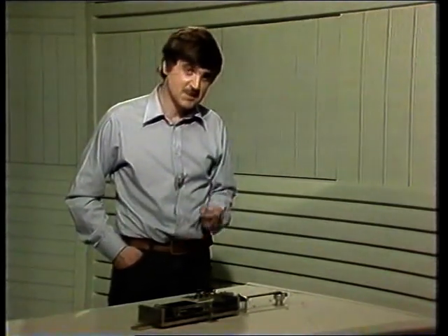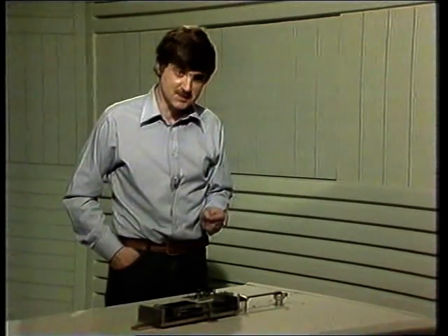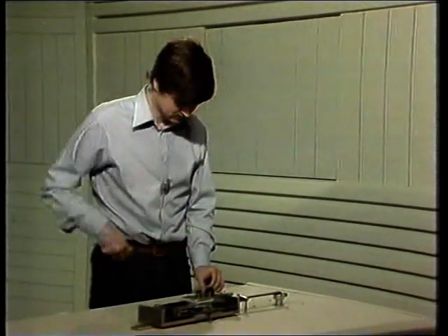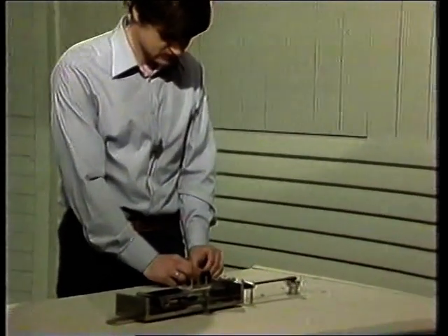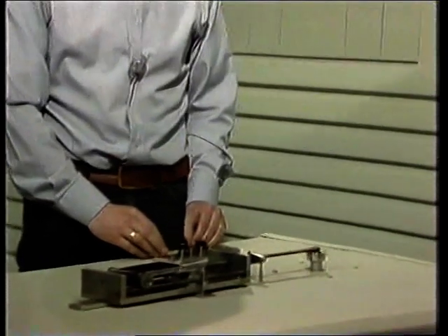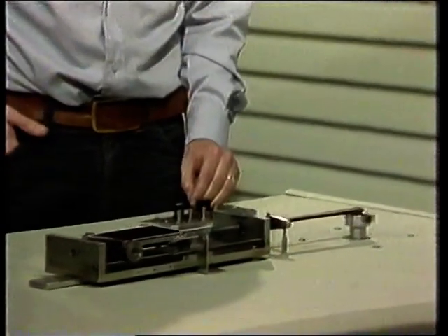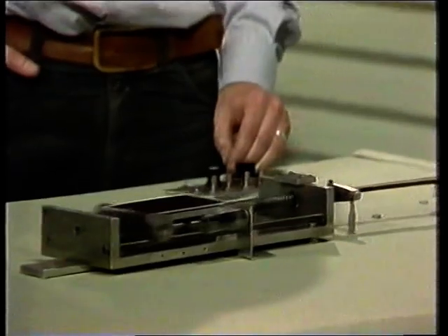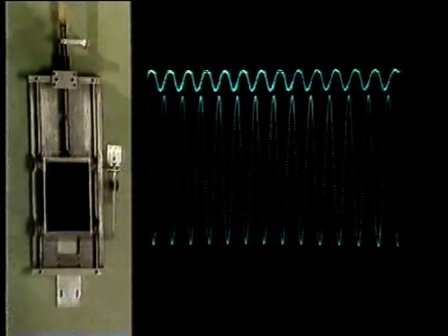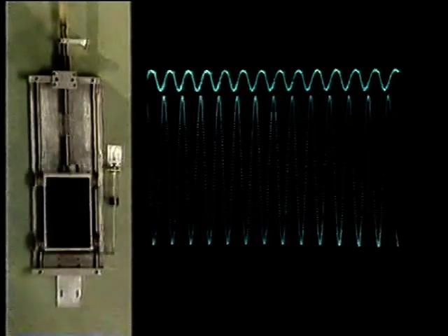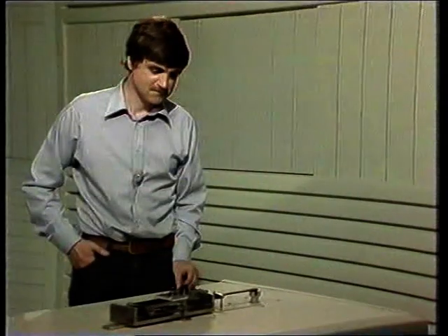For example, if I were to increase the frequency of the input disturbance to a higher value, the system goes into rather drastic oscillations. And this shows up as a large output amplitude in relation to the input. So the system behaves quite differently for different input frequencies.